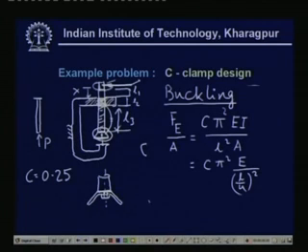But if L is very small compared to K, now I did not mention, K is the radius of gyration, and this is nothing but the square root of I by A. So, this is the radius of gyration, and we have this formula, C pi square E by (L by K) square. Now, whenever L is very small compared to K, we can see that F_E could be very high, but in fact it does not happen, because before it reaches a very high level, the material will be crushed. So, it will be smashed, and we do not allow that.